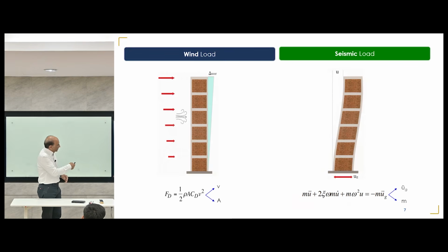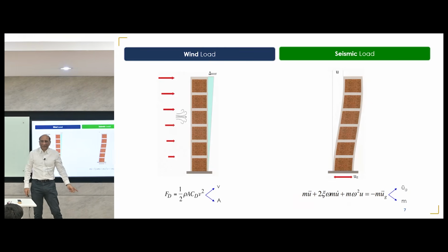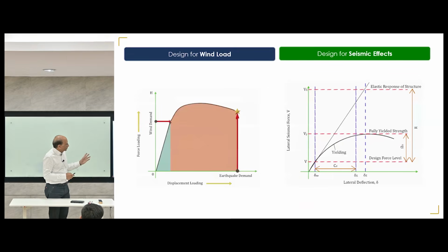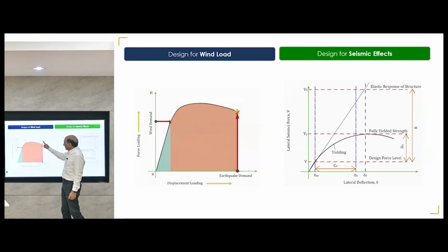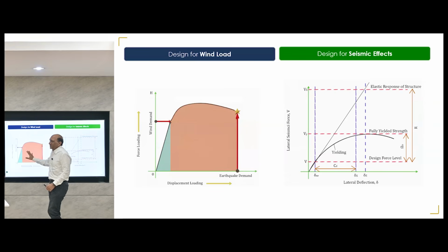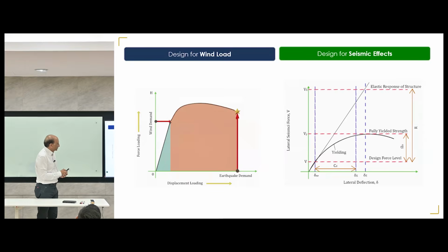We are going upwards, and that equation I showed you earlier, we need to get back to this equation now and try to understand how it is developed first and how it will be used. This one we already saw. We need to now talk about all of that: linear, non-linear, earthquake demand, how did we get here? How do we analyze? How do we calculate the displacements? How do we calculate the force? How do we reduce it? How much factor will we use? All of those details that we have seen before, now we need to get down to calculating them.